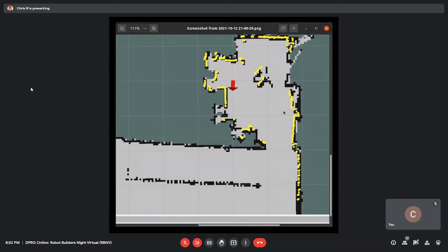It keeps trying to figure out, okay, odometry is telling me I'm here, but the laser scan's not quite matching up, so I think I'm really a little bit more over there. That's what's going on constantly in the background. And so after 5 minutes, it's right back there at 0, with pretty much a perfect heading. So that's the localization in action.